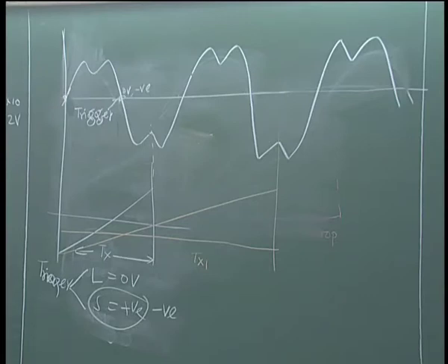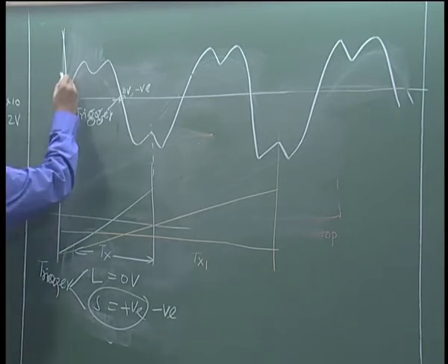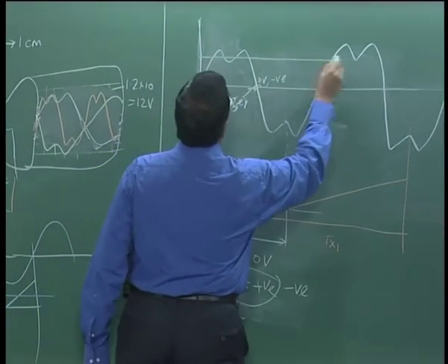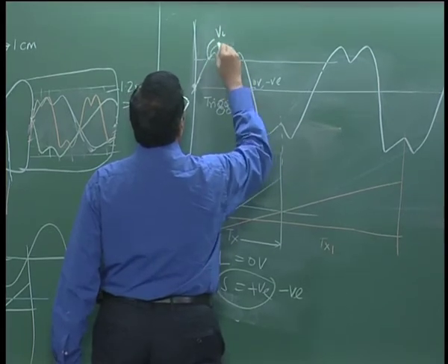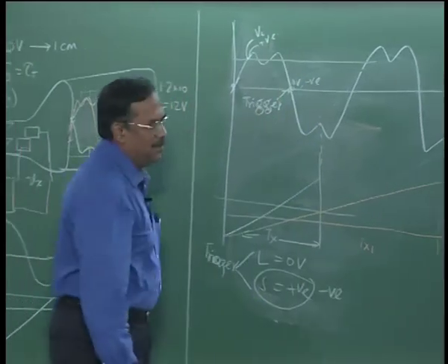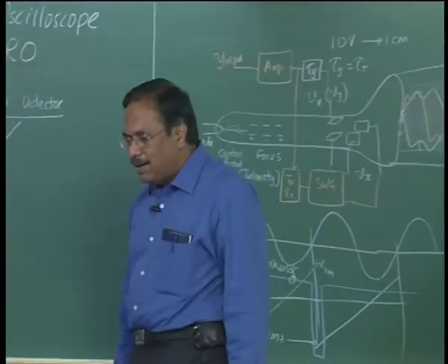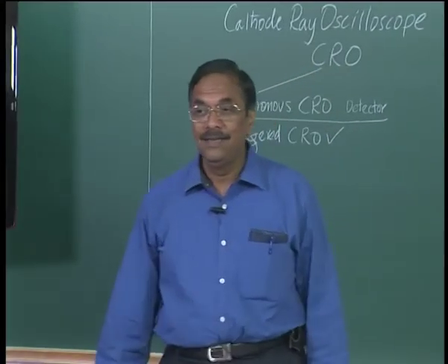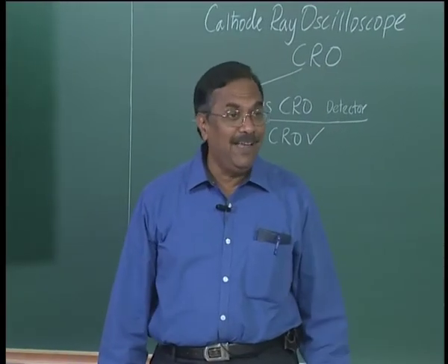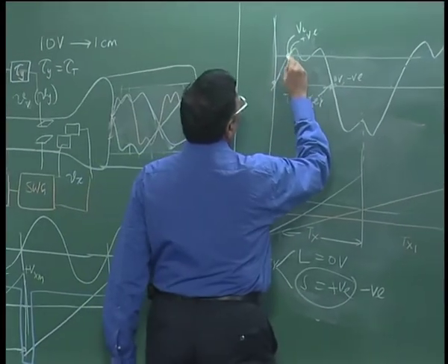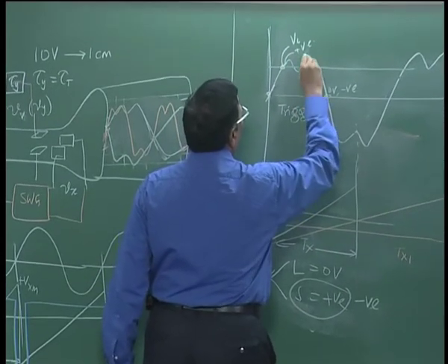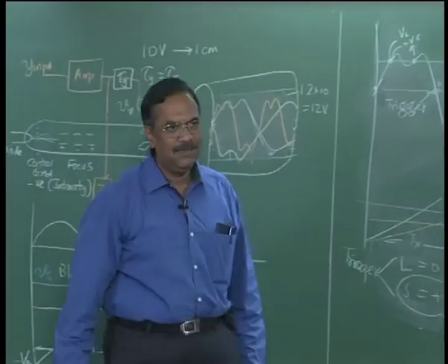And for example, we decide that the slope is positive and this is V level and slope is positive. What do I see now? There are two distinct points that satisfy this criteria, right. This could be my trigger point, slope is VL and positive, this is also VL and positive, right.